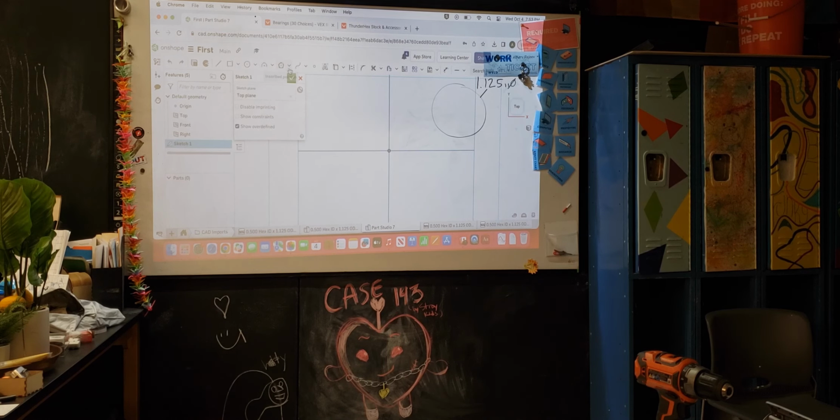Maybe you've experimented with arcs. I'm gonna use an inscribed polygon and click over here, and I click and drag. Boom, and I click again, and once I click, it'll go into this prompt of how many sides you want to make. You don't have to have it exact. You can just click, and then you can edit after.